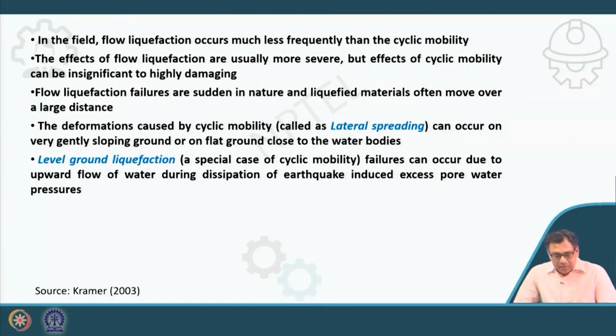Level ground liquefaction, which is a special case of cyclic mobility, can occur due to the upward movement of water during dissipation of earthquake-induced excess water pressure.